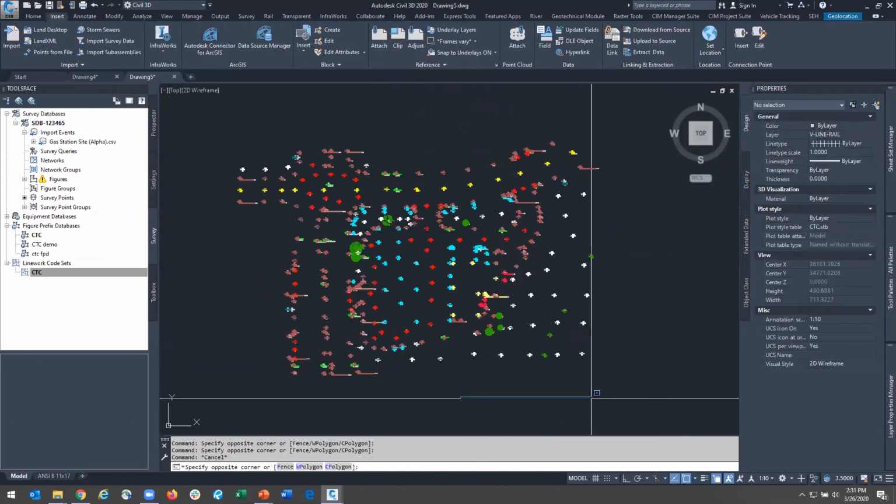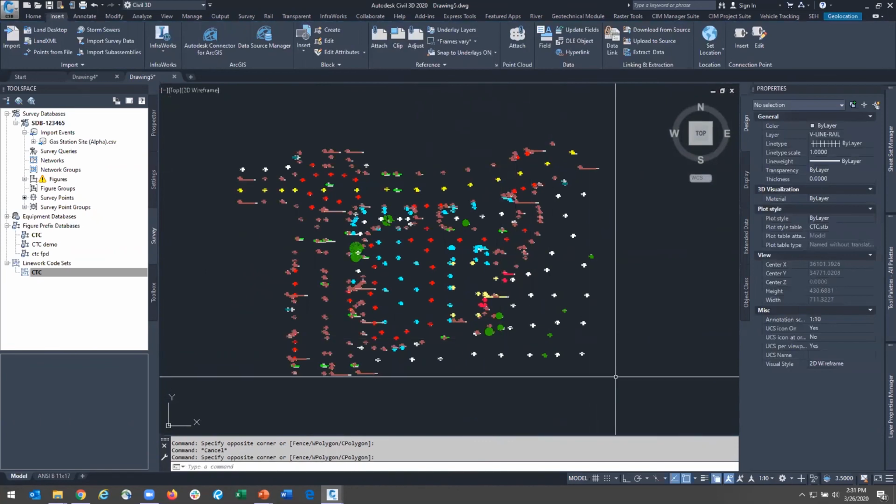So Point File Converter is really great when you're working with another firm who has different standards than yours, but you still want to be able to share the survey CSV files and that output information, but you don't need to share all of your Civil 3D template info. You don't have to give your survey field crews a different code list, and then they accidentally forget that a ground shot is a GS for you, or it's an SG for some other firm, and then now the things just aren't going to work quite right.